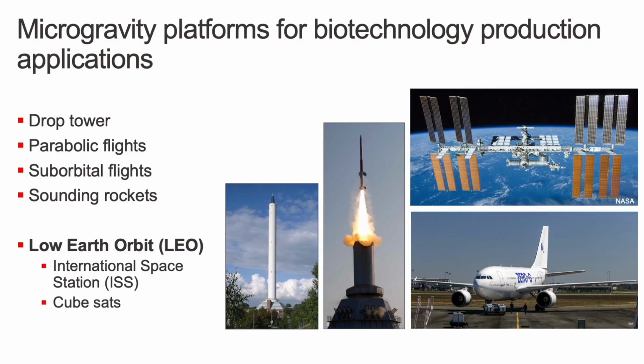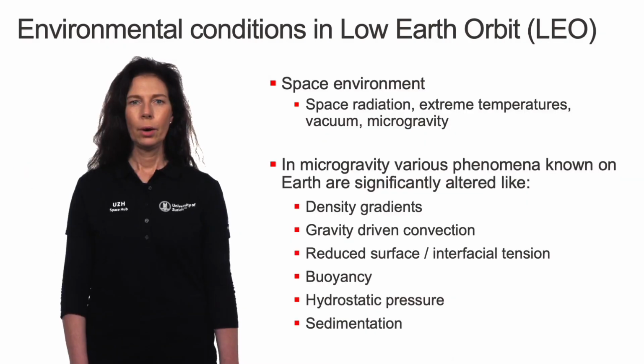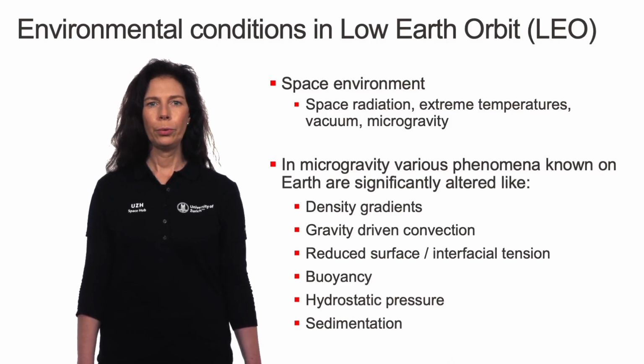This slide gives an overview of the different microgravity platforms. The drop tower allows experiment times of up to 9 seconds. On parabolic flights, 22 seconds of microgravity time can be achieved, while on suborbital flights and sounding rockets, the microgravity time is in the range of several minutes. If longer exposure times, like days or weeks to microgravity, are needed, the International Space Station or even CubeSats are the platforms of choice.